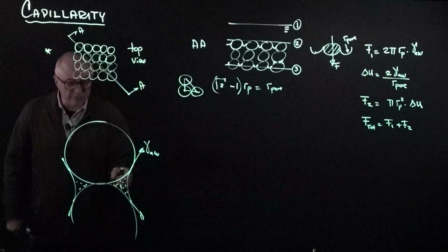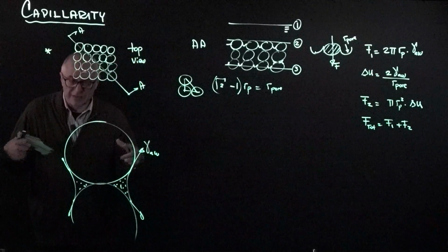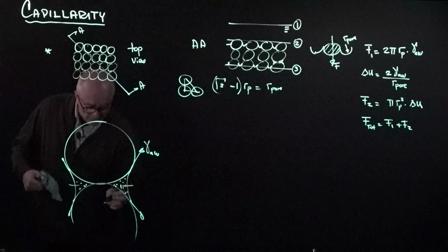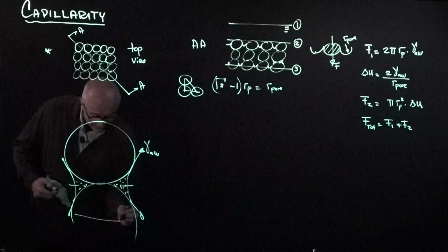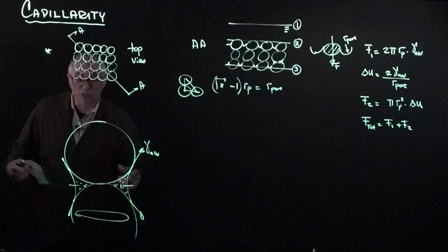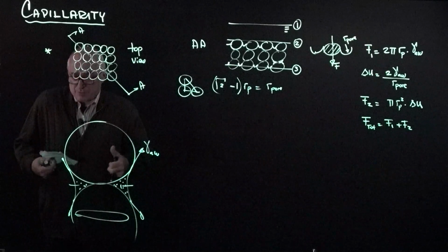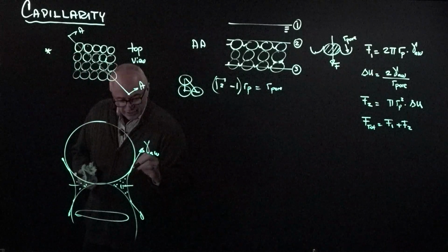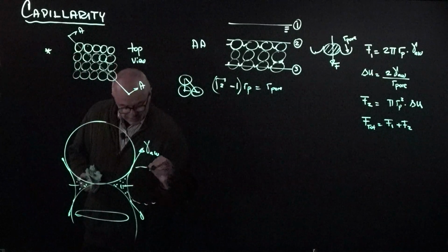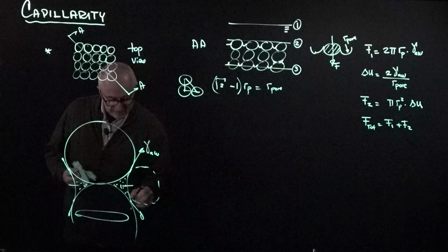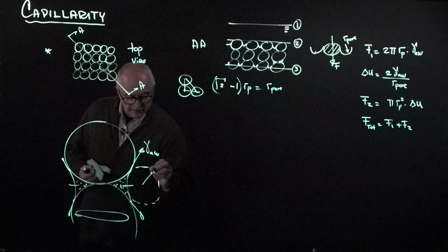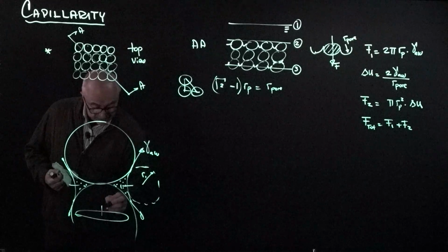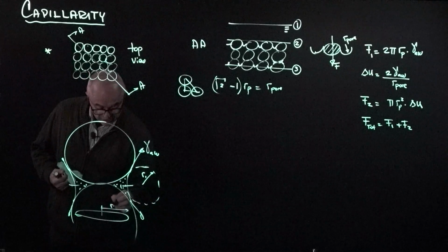On the other hand, because of the tendency of the interfacial tension to contract, if I look at what happens on the equatorial plane, this equatorial plane wants to contract and increase the pore pressure. So now I have 2 curvatures. One is the curvature of a circle that would be tangent here if the contact angle is 0, and so we're going to call this a radius 1. And then we have the radius of the meniscus at the middle plane, which is radius 2.